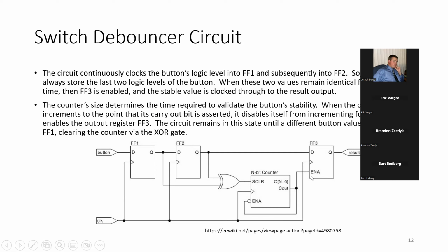Okay, when will it go? If this enable is high. And when will this enable be high? If the counter operates and it reaches the terminal count. If I say my terminal count is 5, I have here high. When will I get S clear low? When I have S clear low, 0, I will start counting. Otherwise, I will never start counting.